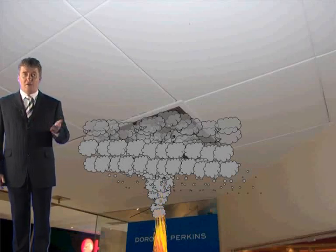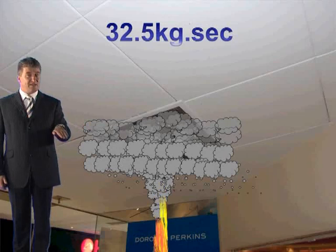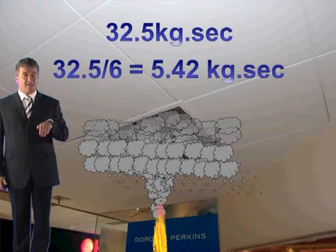The amount of smoke that leaves each ventilator is your total amount divided by the number of vents. We worked out the M, the mass flow rate, as 32.5 kilograms a second. We know there are 6 ventilators, so we divide by 6 and get 5.42.